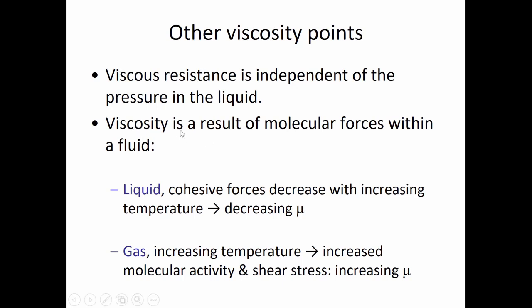What causes viscosity is molecular cohesive forces. In a liquid, as you warm it up, the fluid becomes less viscous because the molecules are moving around more quickly, and that decreases their cohesive forces. But ironically, in the case of a gas, viscosity increases with temperature. So gases become more viscous as they're heated up, not less viscous.